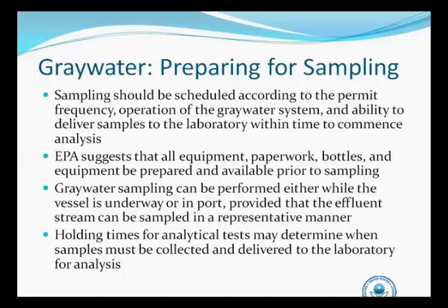The shortest one that you'll encounter for gray water that has its test done in the lab is for fecal coliform or any kind of bacteria. And this time is 8 hours. So a lot of the coordination of your sampling is going to depend on your ability to collect a sample and then have the laboratory commence that test within 8 hours. Each of these tests has its specific holding time, and each of these really needs to be met for results to be acceptable. Next slide, please.